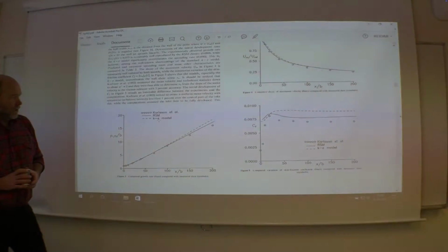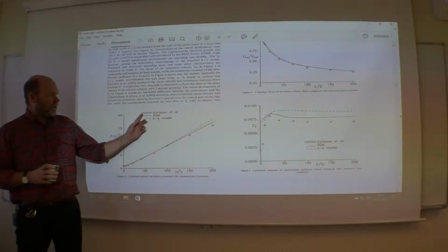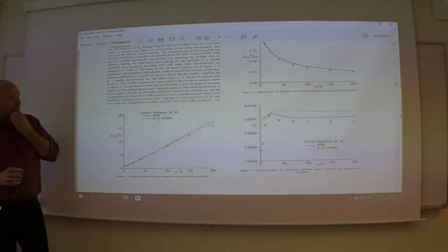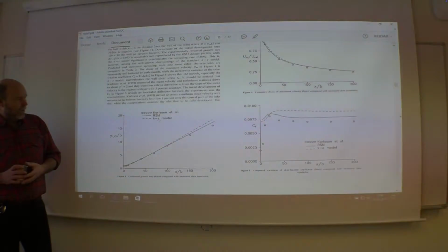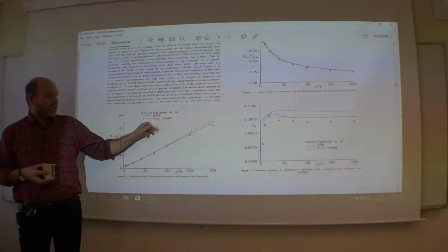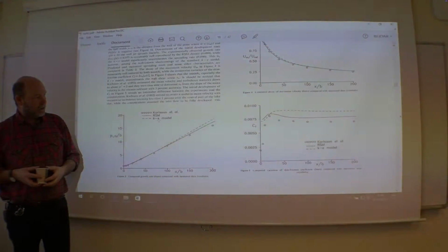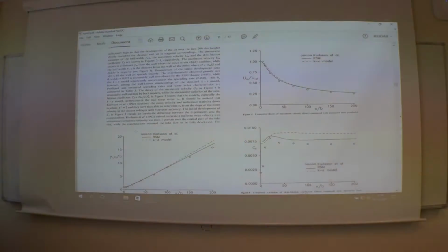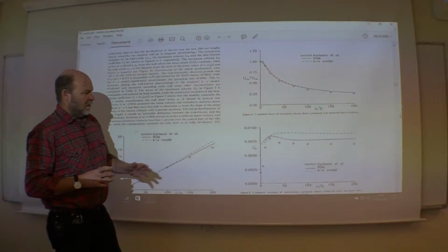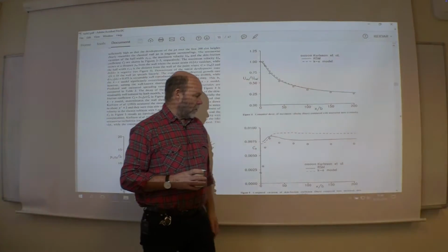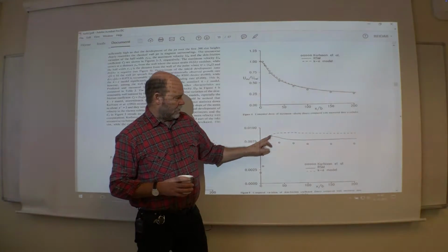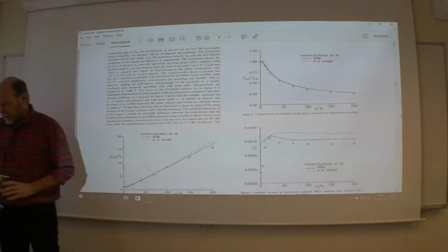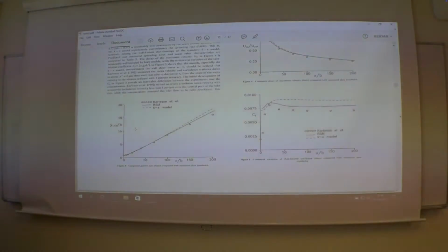follows the bottom wall. They have compared here with some experiments done by some guys in Göteborg, I think. And then the full Reynolds stress model, and then compared with the K epsilon. So not totally stupid, but at least here you see the K epsilon is rather way off, while the full Reynolds stress model follows the experiments much better. So CF being then the skin friction coefficient alongside the bottom wall.